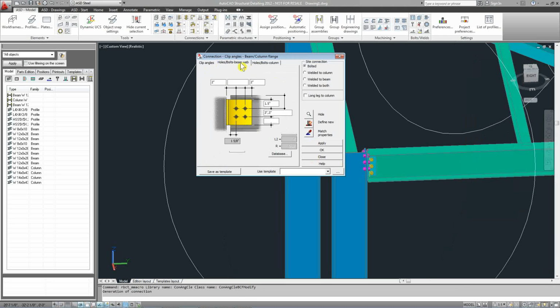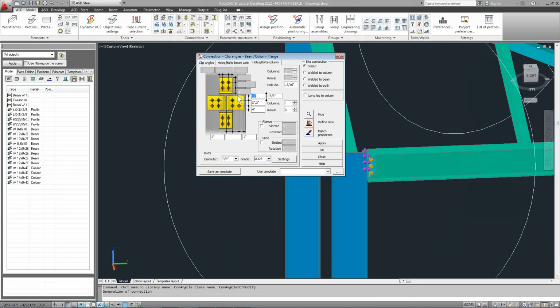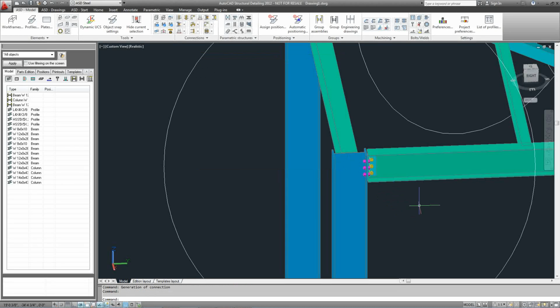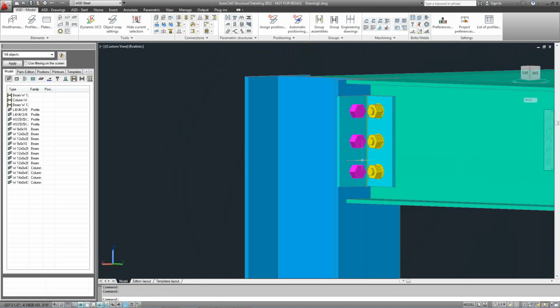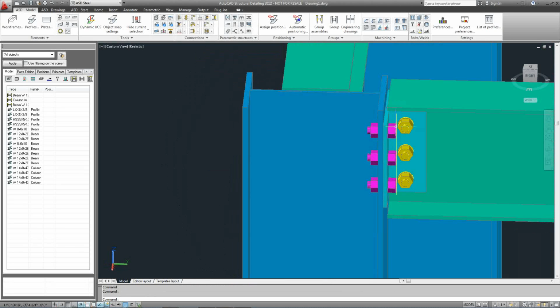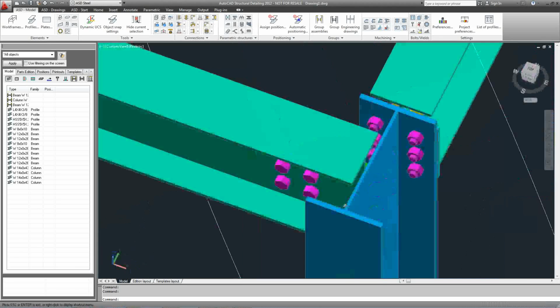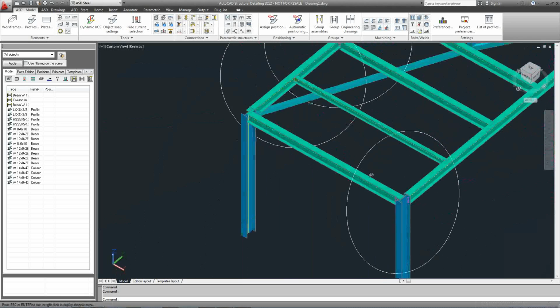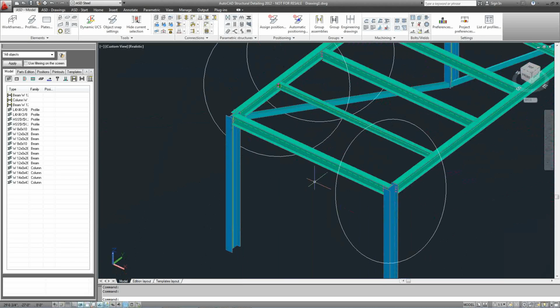Here's getting closer. Here's the other problem. So this is actually nice because if you wanted to set in a stagger, you could. If you wanted to have the web bolts and the bolts into the column different, you can set that stagger based on this first bolt location. I think after all of those tries, we got the connection we want. That's looking a little better. And this also gives you a chance to check for interference visually. You can see if anything is clashing, and our connections look pretty clean. So what we're going to do next is look at creating some shop drawings from these models.